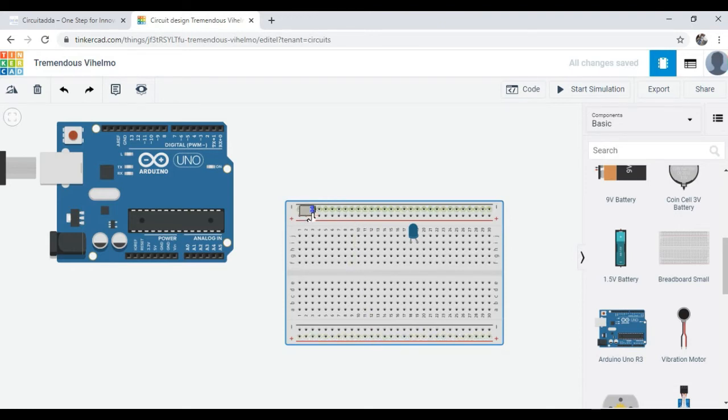And for this connection, if you place a positive terminal here, then the whole row, starting from here up to that end, will get short circuited. That means if you use one pin here, and you connect some other component here, these two components will get interconnected in the background, because the whole line is short circuited in the background. Similarly, this line also, similarly this one, and similarly this one. So whatever horizontal lines you have in the breadboard, all of these horizontal lines are short circuited in the background, right?